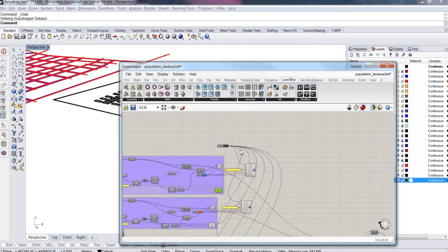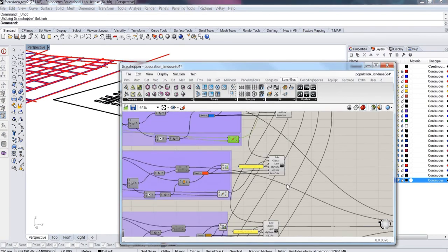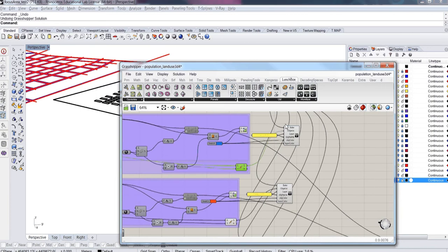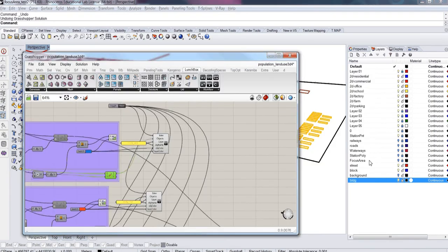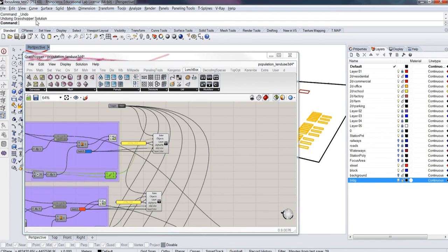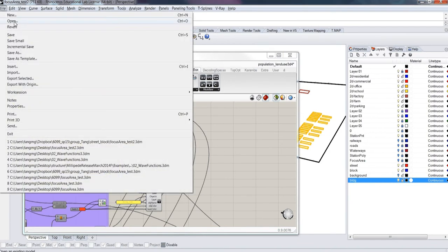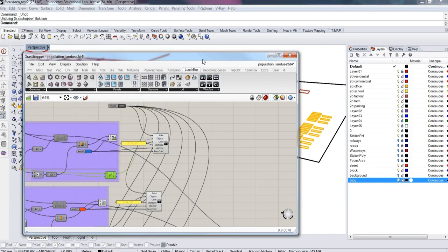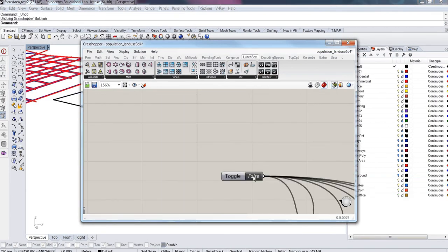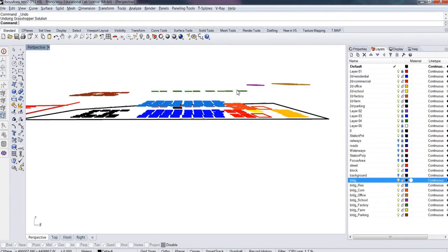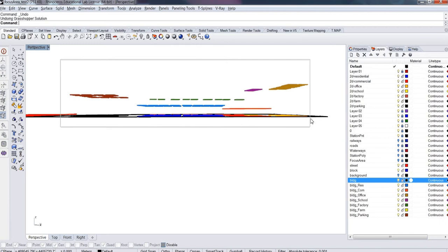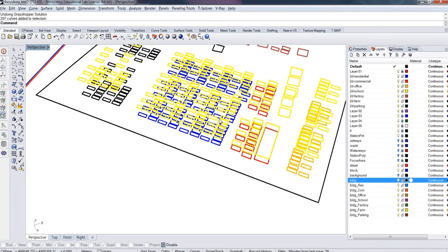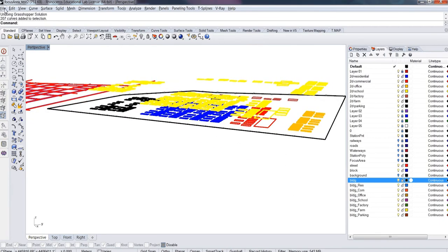Alright, I think that's it. This is how you bake the geometry into the right layers. And then later, after you have this, in order to give this to the Scenarios 360 team, let me just bake it really quick. Bake it and then turn it off. Close Grasshopper. So what you need is you give them these files. This floated elevation file, you can export as a DXF.